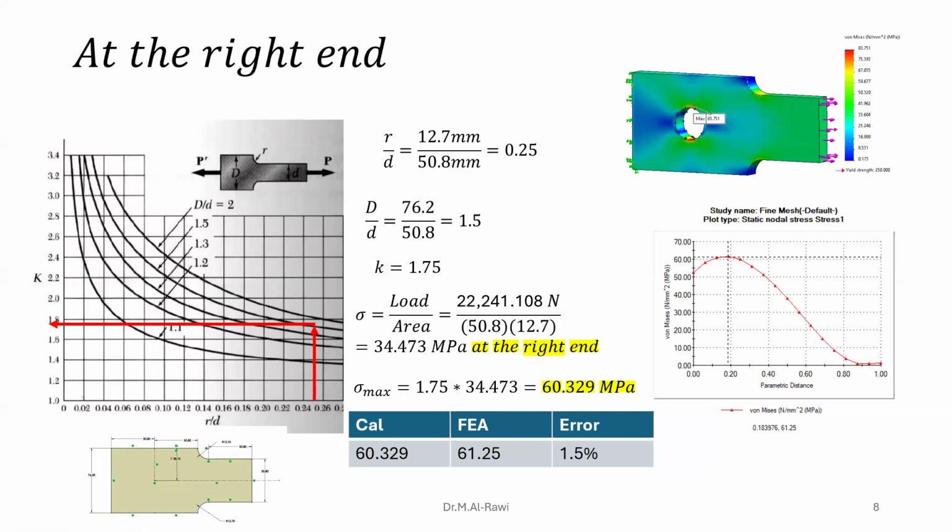Remember, this is not the weakest area. This is the second weakest area because it's showing there is a high stress distribution. Now, what did I get from that? If I select only von Mises, it only shows me the maximum, which is 83.71 and is actually here.